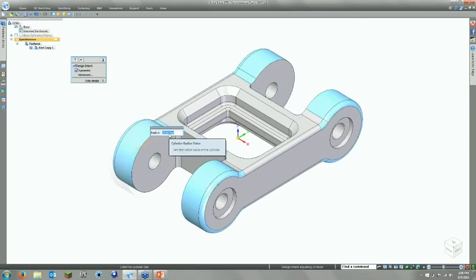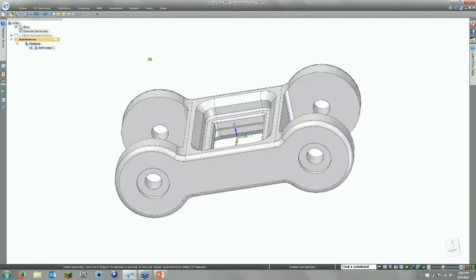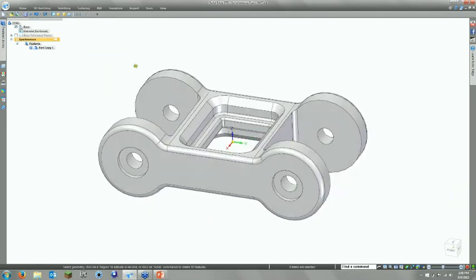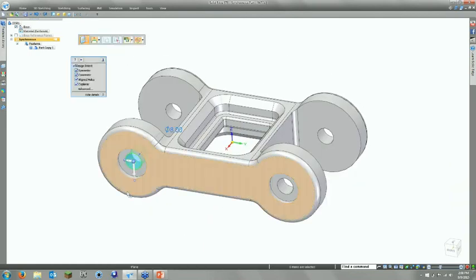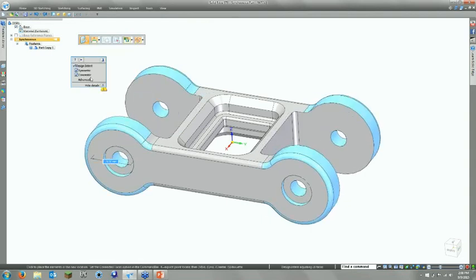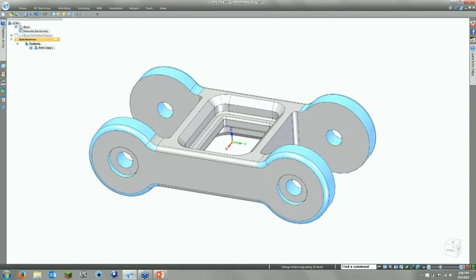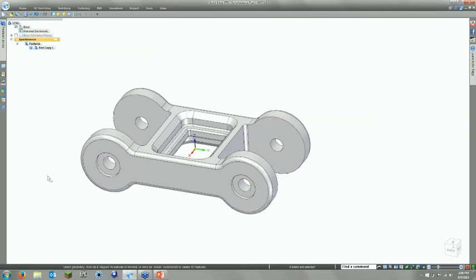All right, so I'm building design intent by nothing more than moving my geometry to the coordinate systems and letting the software interrogate it and see what's going to be needed. All right, so let me undo those couple steps. All right, so the first thing I know I need to do is I need to make this part longer. So as I pick it, now my bar is going to have considerably more features. If I grab that, now I have concentricity, symmetry, tangencies, etc. And again, it doesn't slow me down. I didn't have to do anything specific.